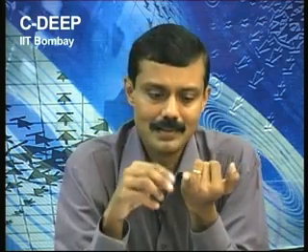I told you, as of now I am just talking about reducing the frequency. While reducing the frequency, I have to reduce the voltage also. Reasons sometime later I will tell you. As of now, I just set a frequency converter. It has to vary the frequency of the output. So what is the relationship between the frequency and the output voltage? We will see sometime later.